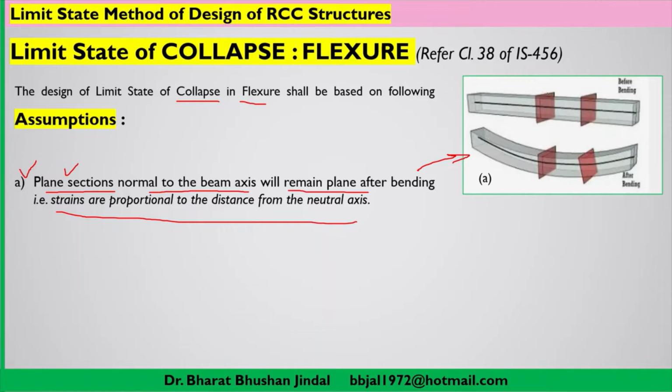So these two sections are initially plane, and you can see here that after loading, the beam will be subjected to some moments, as I have already told, and due to those moments there will be some bending in the beam. You may see here that the top fiber of the beam is under compression and the bottom fiber is under tension, as we have already studied in the bending theory.